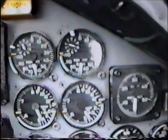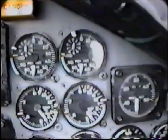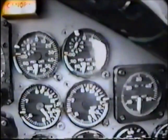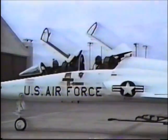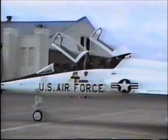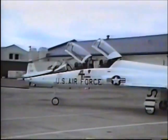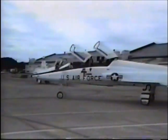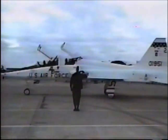A throttle setting of approximately 70% RPM should be sufficient to get you rolling out of the parking spot. Once moving, use minimum power settings while in the parking area. Your exhaust could damage other aircraft or injure personnel in the area. When near other aircraft or in a congested area, your taxi speed should be no faster than a brisk walk. Since it's difficult to judge your speed while looking straight ahead, keep glancing out the side of your aircraft to monitor your speed.